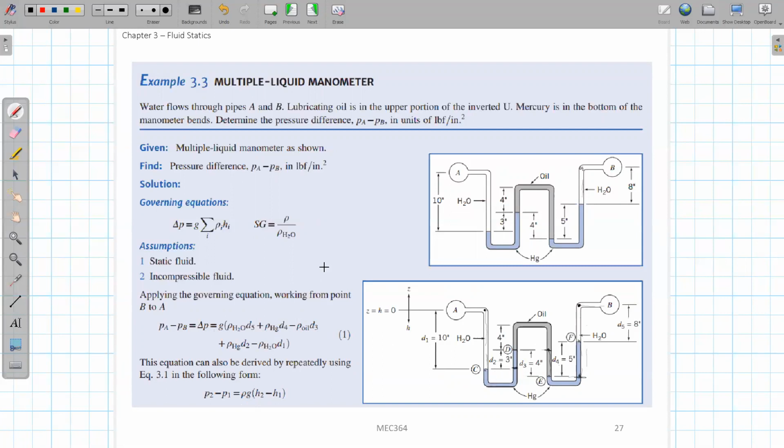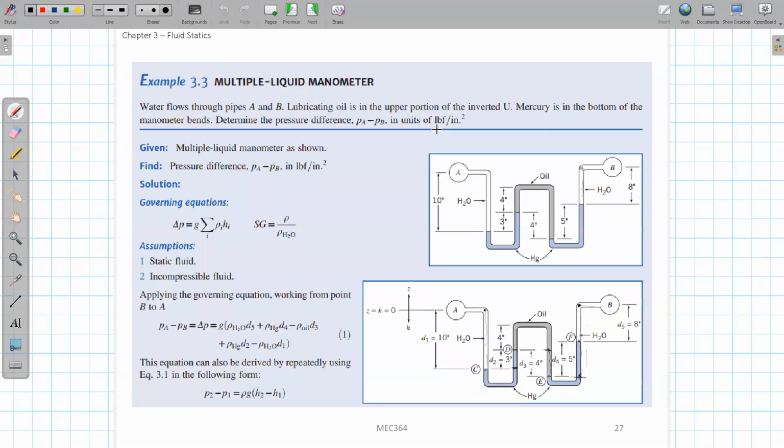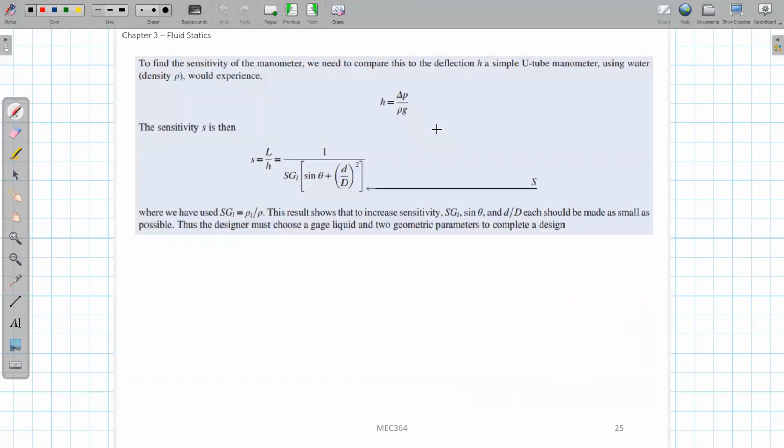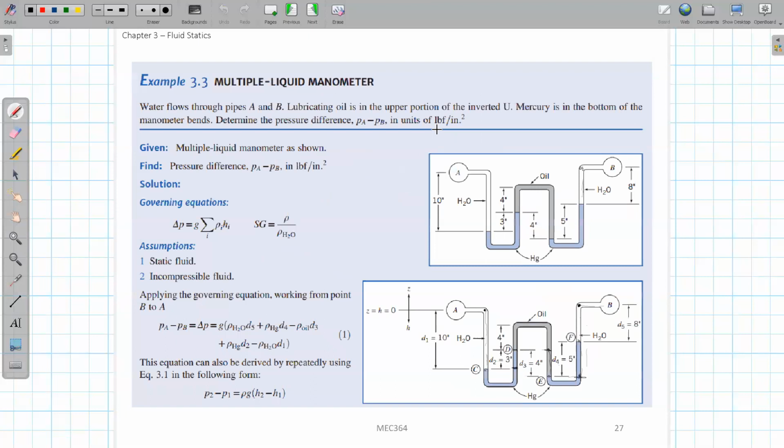This equation just gives you a shortcut, because when I follow the passage of the flow from right to left, we can quickly write this summation. So this is only a shortcut equation. And if you do not want to use it, you can still use the original equation to calculate the pressure at each point.